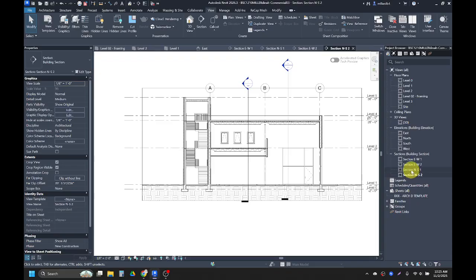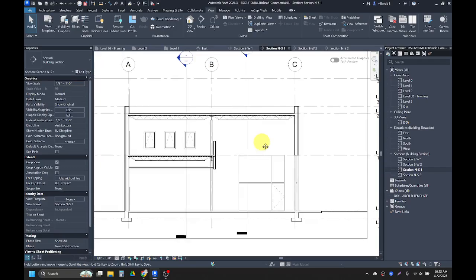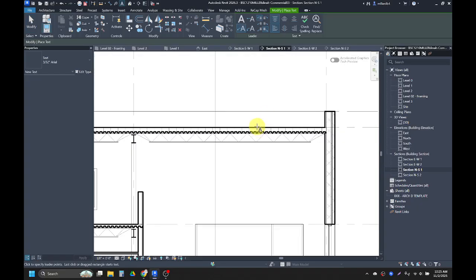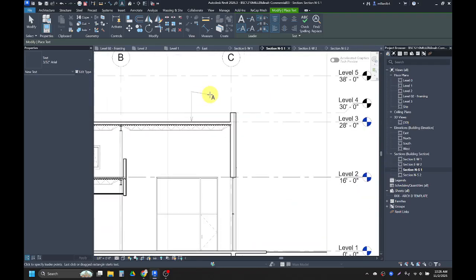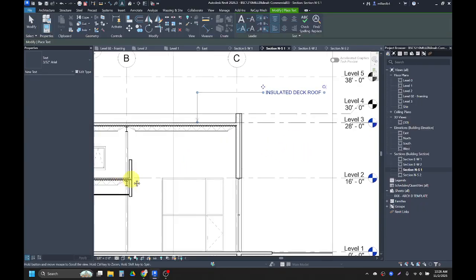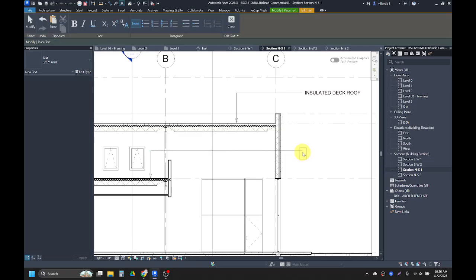And then in my north-south view number 1, we have a few annotations and details in here. So again, that would be the keyboard shortcut TX for text, where we can point, come out, and over, and then I could type my text. I could also go for my composite deck floor.